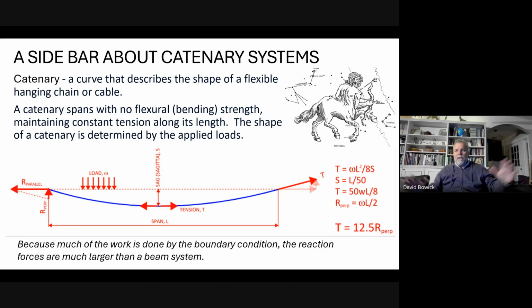That's my vertical load. It's nice and light. Anything can take that. The lesson here is that if the perpendicular load is 500 pounds, the in-plane load is 6,000 pounds. The in-plane load is dramatically higher than the perpendicular load. But the perpendicular load is the one that we can get our heads around. So people dramatically underestimate the amount of in-plane load.